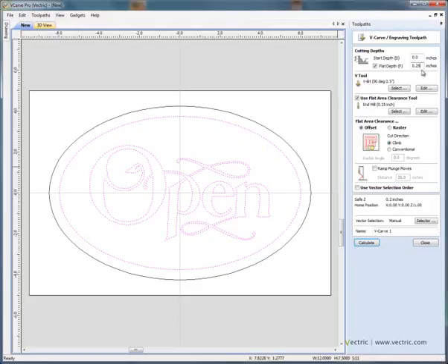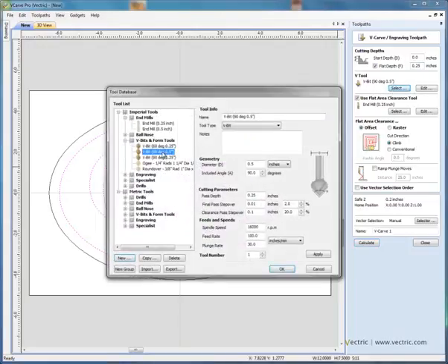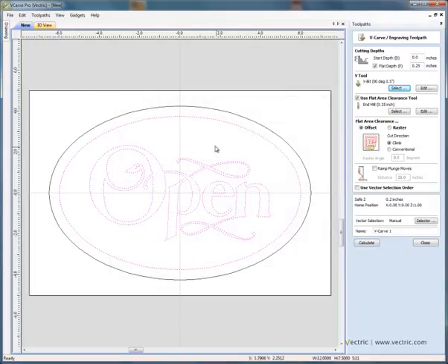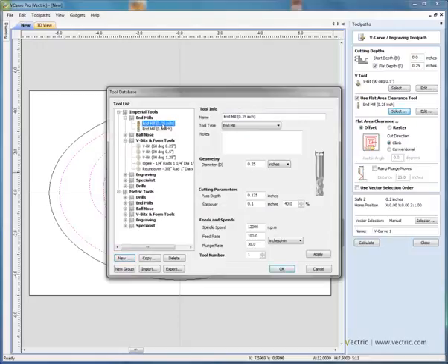We're going to cut the toolpath 1/4 inch deep. We'll use a 90-degree V-bit cutter to get the detail. But because we've got some large flat areas here, we're going to initially use what's called a flat bottom area clearance tool. For that, we'll use a 1/4 inch end mill.